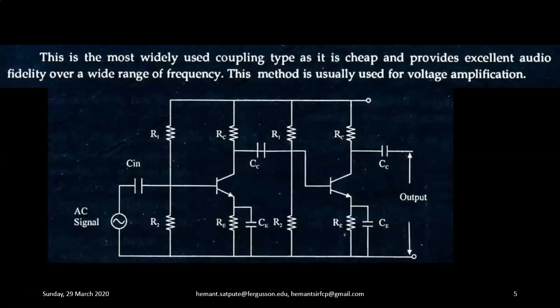Now let us see, when this question is asked, what exactly to write in the exam. So in the exam you have to first draw the circuit diagram. So this is the circuit diagram. This is the most widely used coupling type as it is cheap and provides excellent audio fidelity over a wide range of frequency. This method is usually used for voltage amplification.